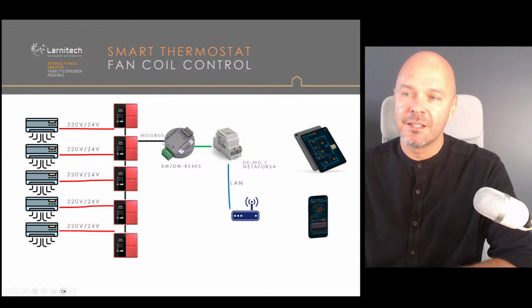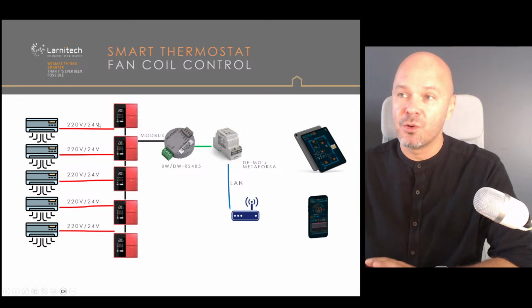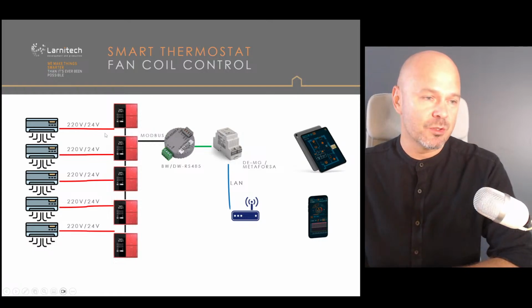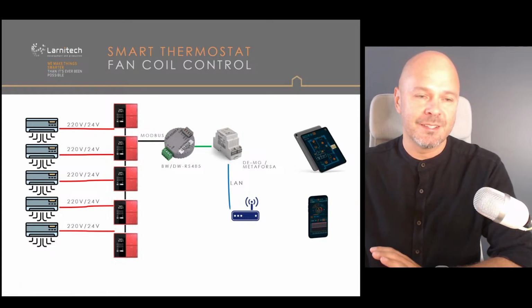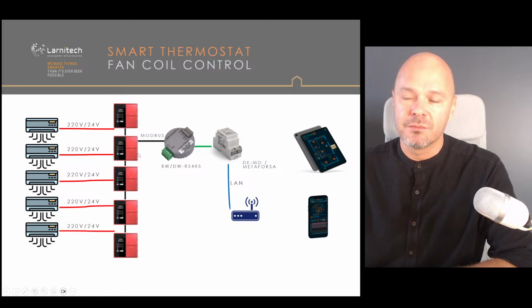And then you need another adapter, and you connect this thermostat to the AC. In the UAE, this is mostly 220 volts, but sometimes for valves and fans, 24 volts is used. 24 volts is more of an American option, what you can find inside Nest, for example. Okay, so this is one of the most common options.